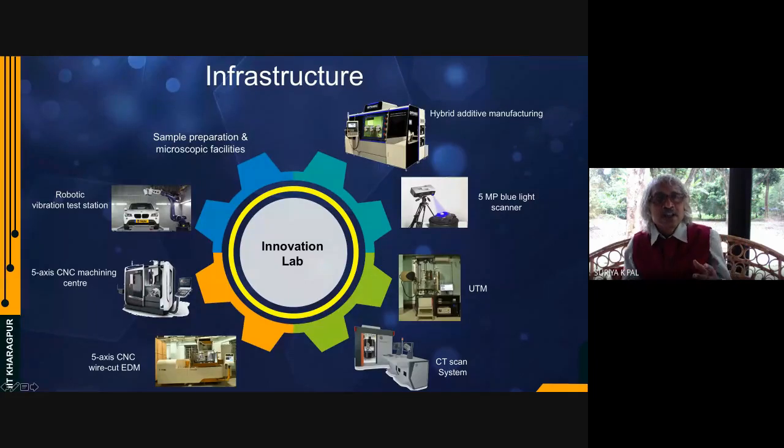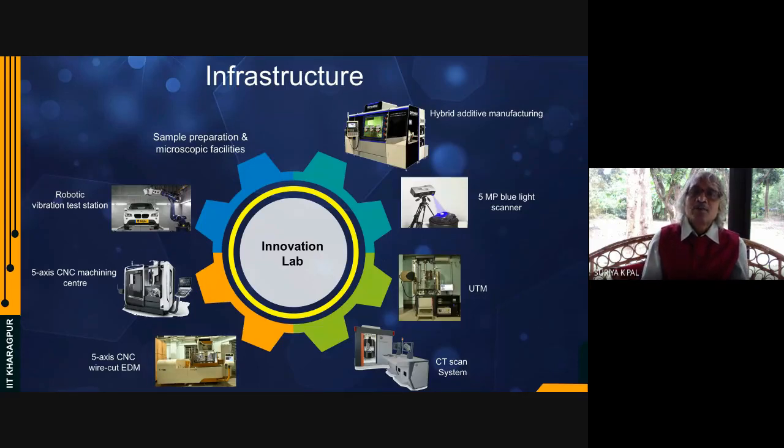If you want to see the endurance or the fatigue life of any component that you are designing, then you have to subject that component to a particular loading scenario for a long time, and check the level of vibration. Mostly this is done by an accelerometer, and in that case a physical contact between the sensor and the physical object is needed. Whereas if you use a laser scanner on top of a scanning facility, it will scan the entire surface for a long period of time, and give you the mode shapes and also the level of deflection of different components when the equipment or the product itself is subject to different loading situations.